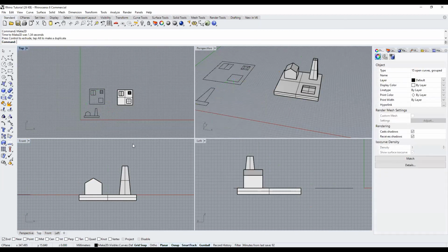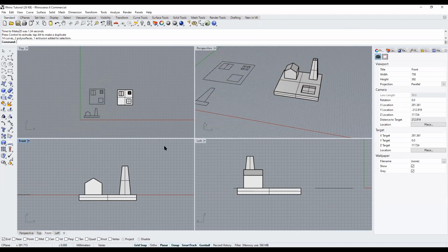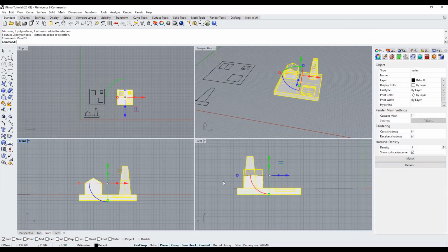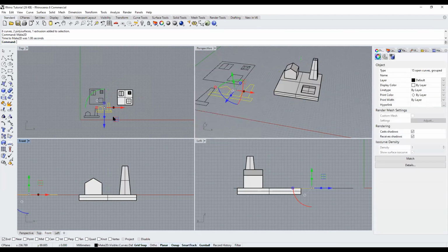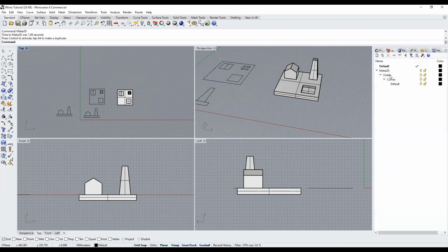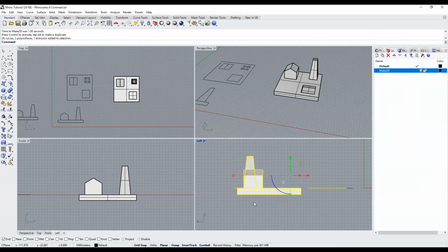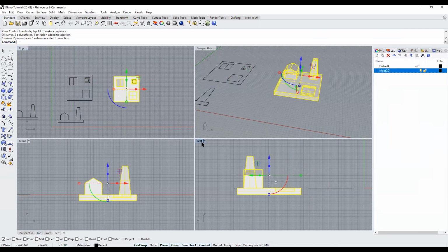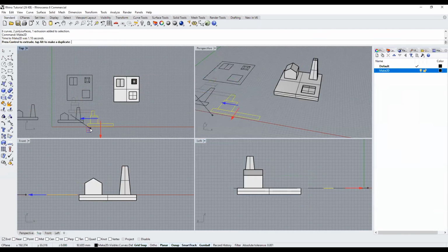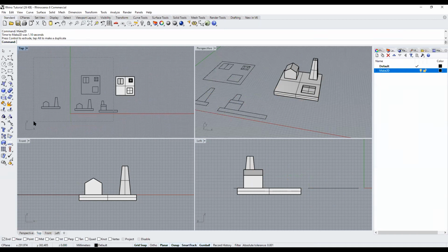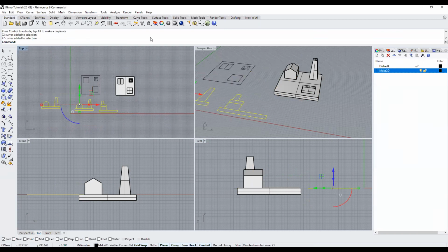When you make 2D, you just need to type it in, press enter, and everything's basically done for you. When you make 2D, it also automatically puts the result onto a separate layer, a new layer called make 2D. And yeah, you can just hide all this if you want. And I want to make a drawing from this side of this side. So yeah, this is how you make plans and elevation drawings.